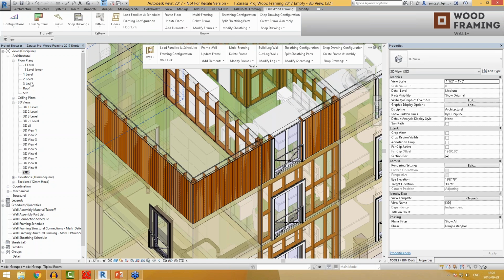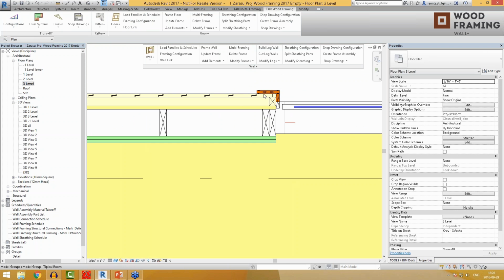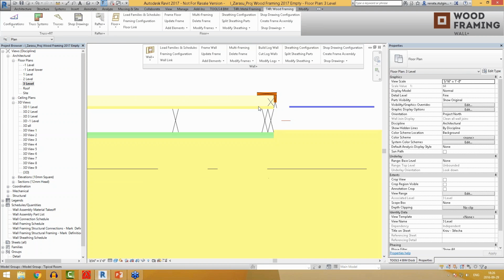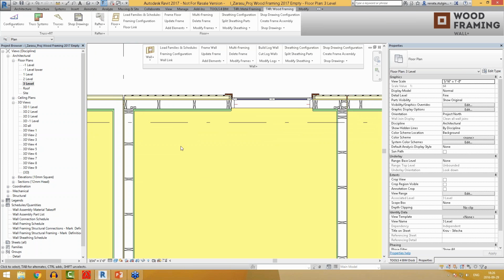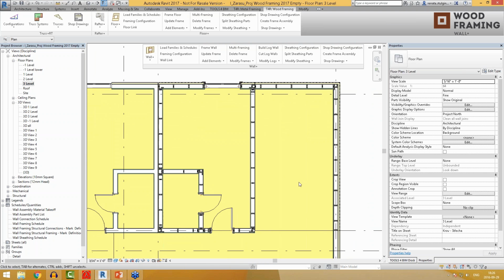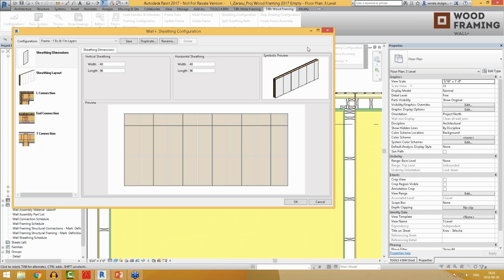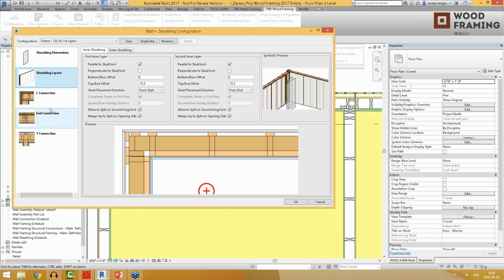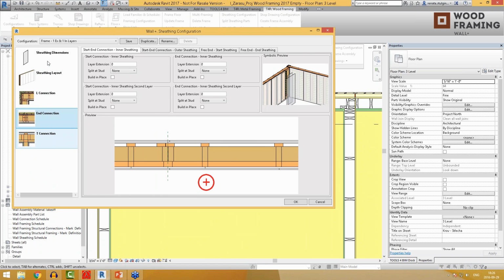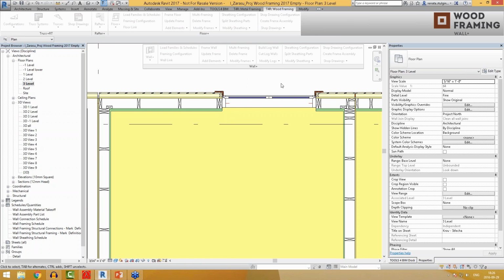Yes, and we can just come back into our plan view. So we see here everything. We have the trimmers and the sidings and the main studs with our predefined corners. And now we can also split the sheeting. Here we have a function for splitting the sheeting into the segments, where you can predefine your own sizes and your own specification for splitting the sheeting.